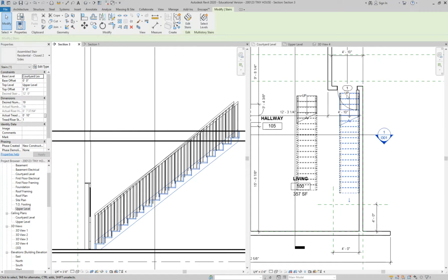Okay, so we're gonna say that this stair just doesn't fit. When I look at the calculations here, I am not quite to the 7 3/4 / 8 inches yet. If I go up to 8 inches, I am breaking code, but just per se, right? So I know that I can actually get rid of one more step and still have it be in code. Are you guys with me there?